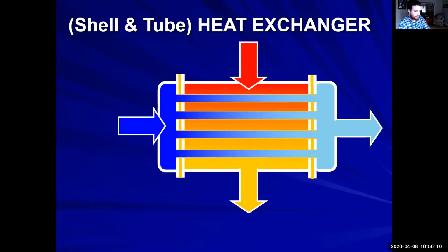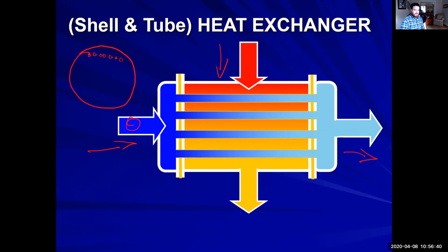To the condenser. On the TSES we are utilizing a shell and tube type heat exchanger, which basically means, as we talked about, all the hot stuff is coming through the top and all of our salt water is flowing through the sides. From the side, if you're looking at this blue side here, it would be filled with little tubes all the way through. I'm not going to draw them all out, but that's basically what you would be looking at. All of those tubes represent one of these tubes that you're seeing here.